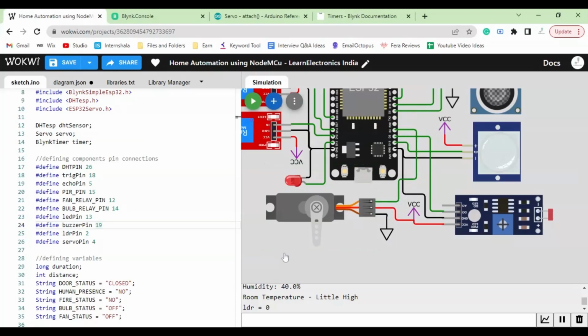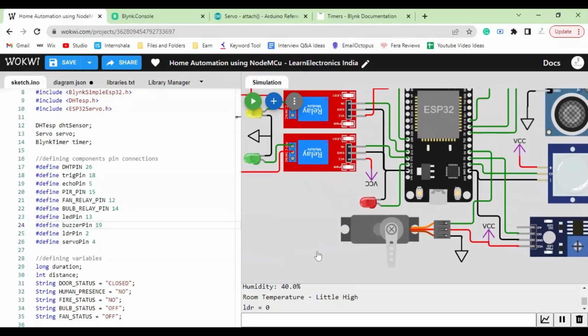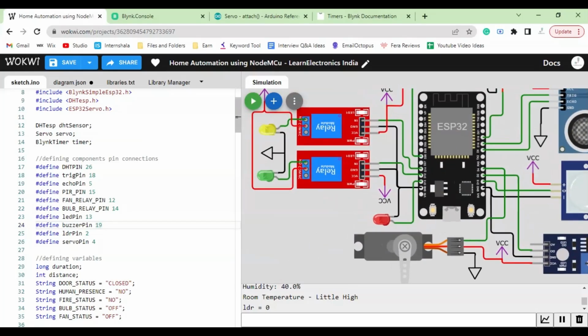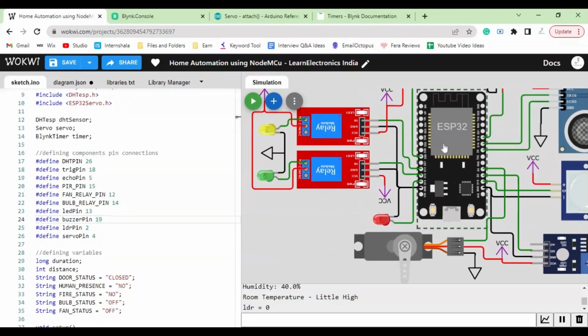So in this manner, we have the pin connections mentioned in this code, showing which pin is connected to which terminal of this ESP32. The basic idea is, now we have told our ESP32 board that in this pin we have connected something, and whatever we will be doing, we will be doing with the use of this variable.